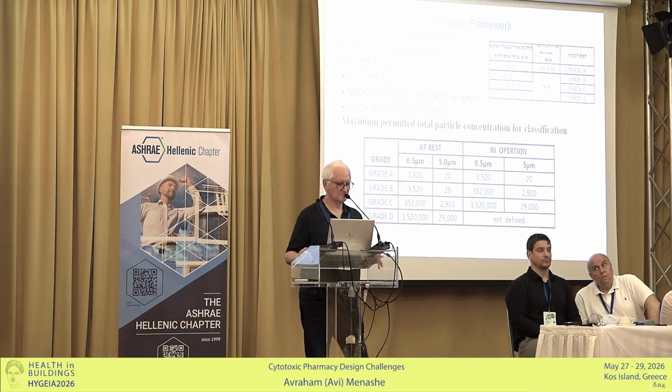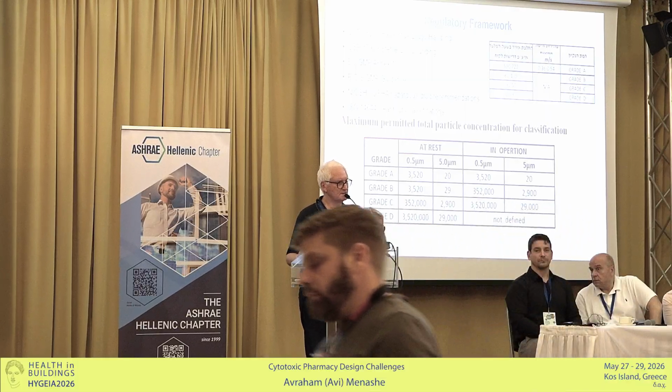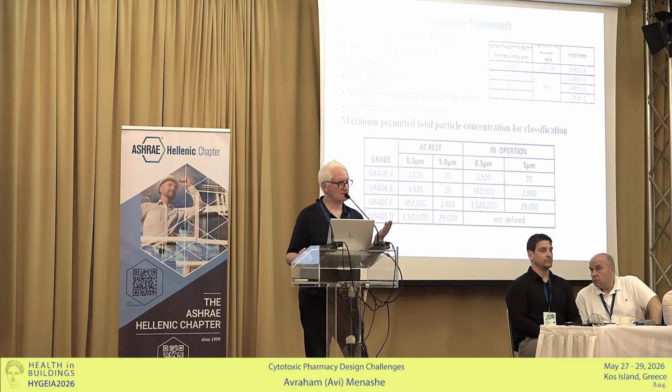So these are mostly the European regulations on how to design it, and the most important thing is to understand that we are talking about clean rooms, but those clean rooms are based on grade level and not on class. If we take class 100,000, which is parallel to ISO 8, or class 10,000, which is parallel to ISO 7, and so on. So in pharmacology, we are talking about grade. Grade A is the highest level, which is close to, let's say, ISO 4, and grade B is like ISO 8.